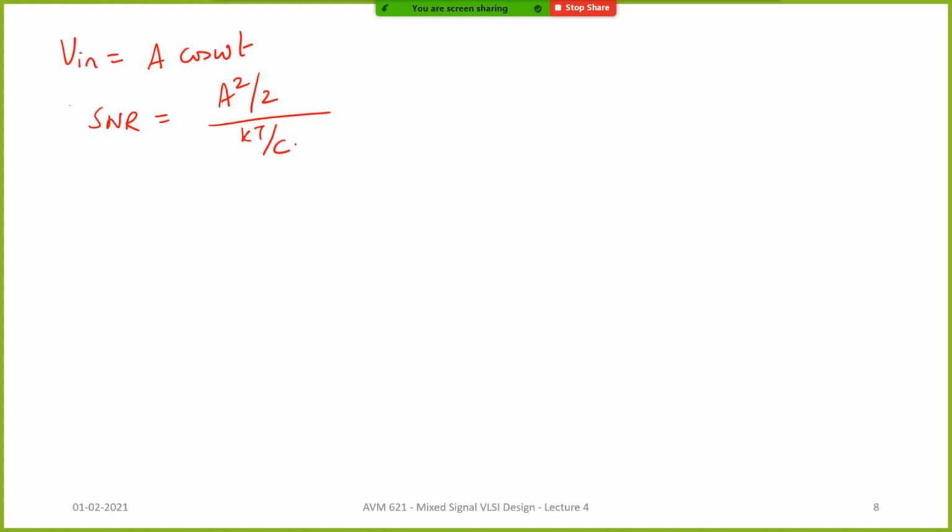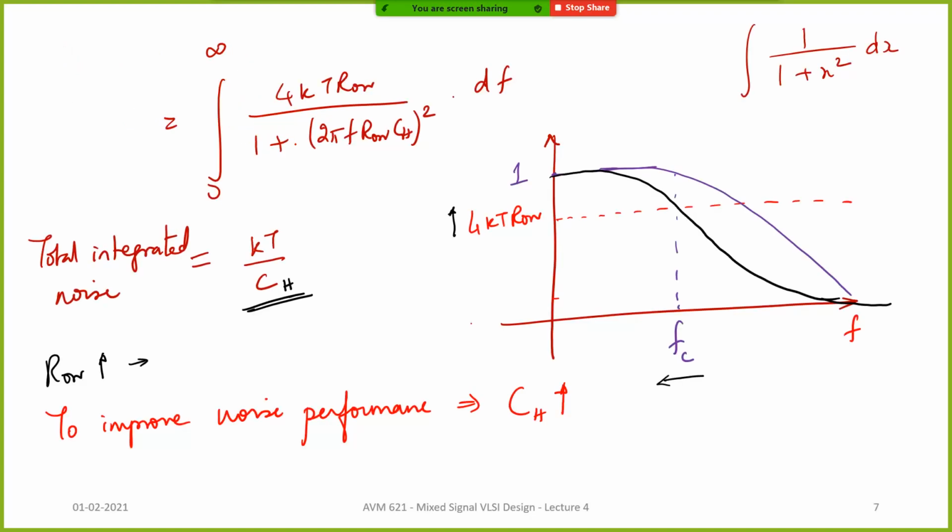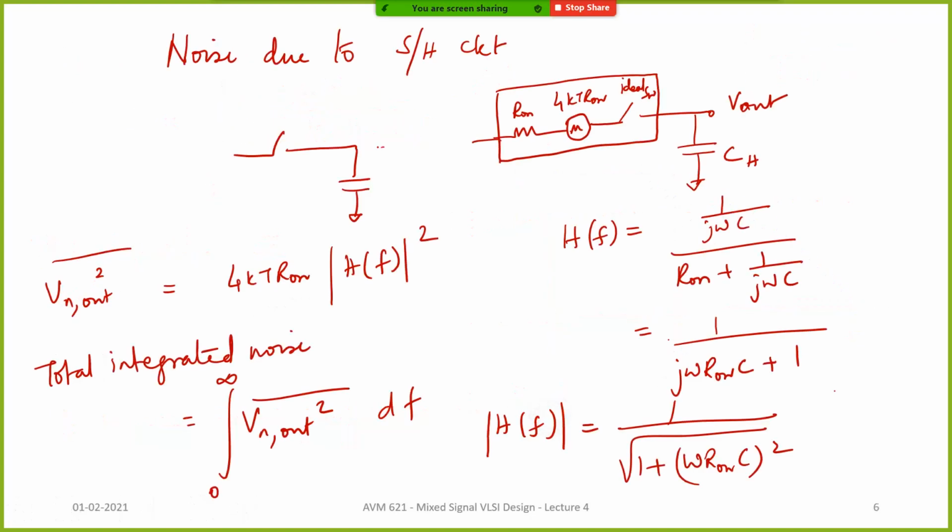This is understood when you are doing this: the voltages are across capacitors and there is no real impedance across which these voltages are being taken, so you just take the voltage squared and leave out the impedance. The notion of power comes only when there is a real impedance. So if across C there was some resistor RL, then we can define an effective amount of actual power.